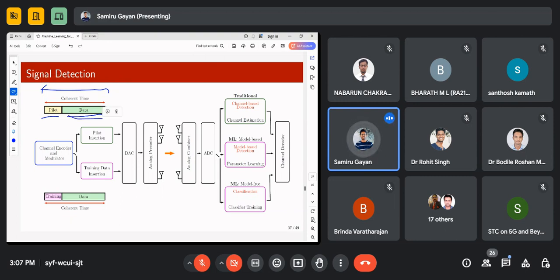Normally, if you take a frame size, you need to transmit maybe 12,000 or 13,000 bits as data, and we need to use a portion of that frame as the pilot symbols as well. This frame actually begins with the preamble.